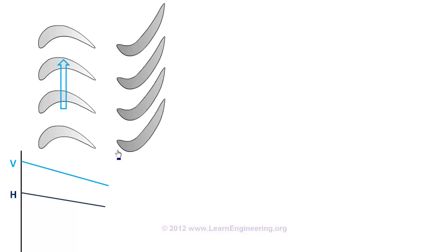Stators are also a set of blades, but these blades are stationary, they won't take part in energy transfer. What they do is simply transform energy from one form to another. Or more precisely, they transform the enthalpy energy into kinetic energy. You can see the cross-section area of the nozzle decreases with flow, so due to its special shape the velocity increases. But at the same time enthalpy decreases. If you sum the change in enthalpy and kinetic energy, there won't be any change.